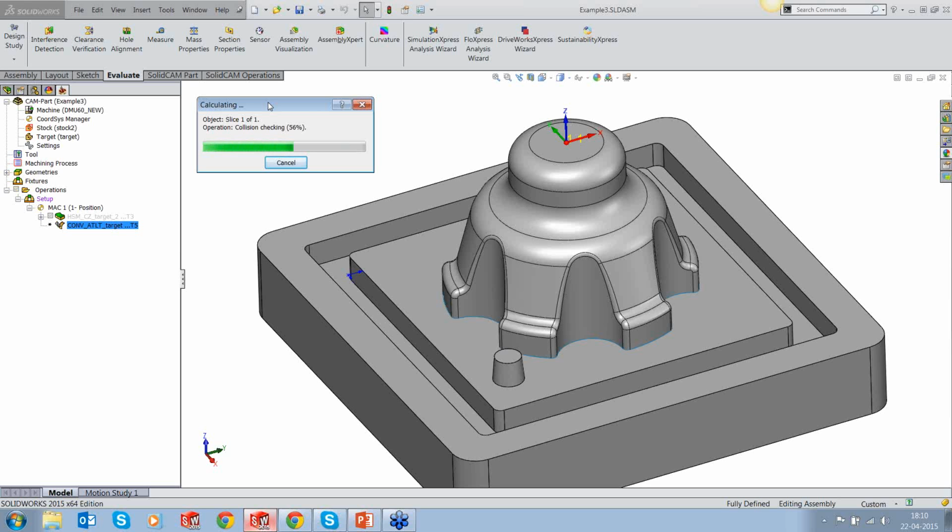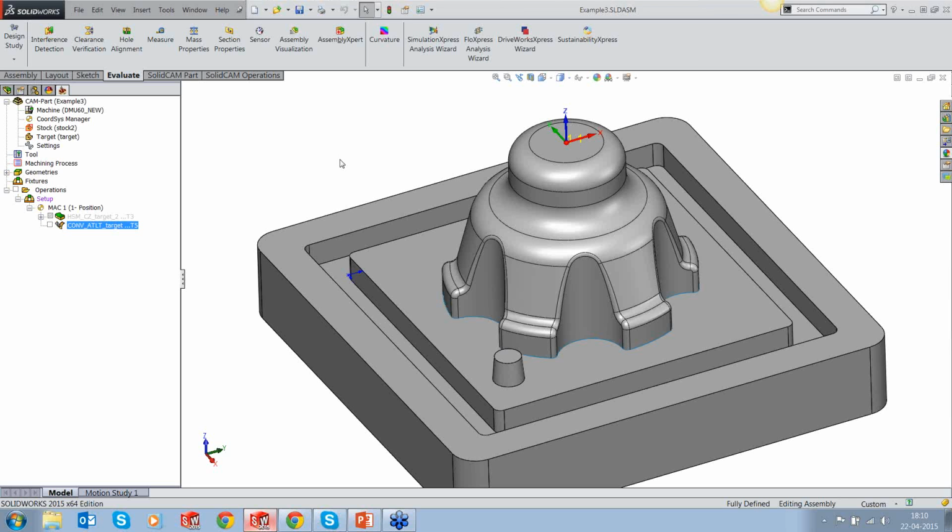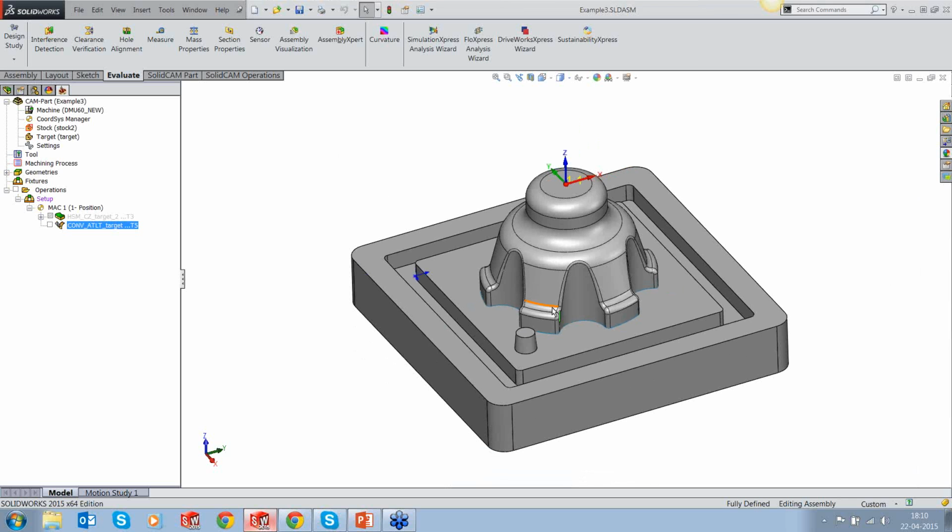And that would provide them with a rigid cutting that would not only improve the surface quality, but it will also improve the time needed to cut the part. It will bring down the time from the existing few hours to maybe 50% of it, because it's using a short tool which is pretty rigid.